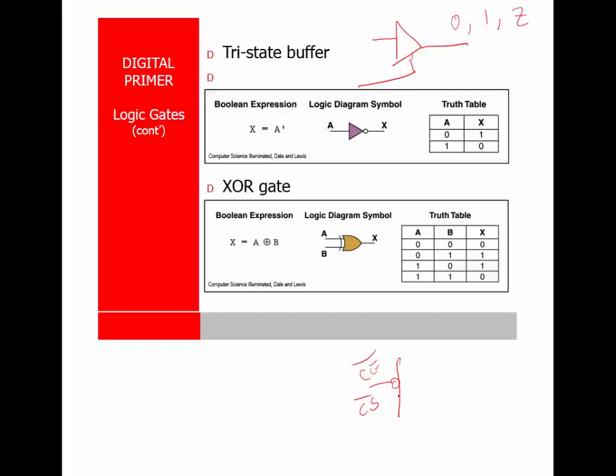But when you see this bubble here, that means that it's active low. That's what that bubble means. So that little bubble tells you that input is an active low. So this particular chip, it's a chip select with a NOT with a little bar across it, so it's chip select NOT. If you look at the schematic for the chip, you'll see the little bubble there.